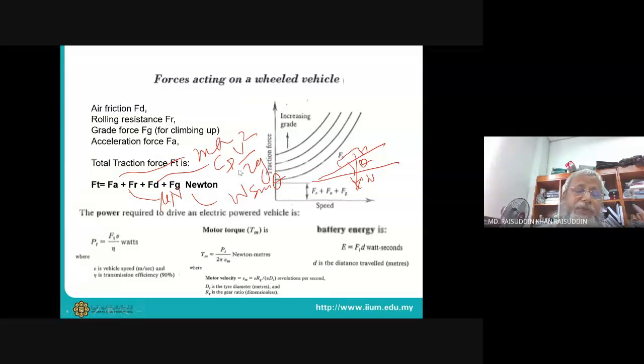And how much power do you need? So this is the calculation of the power. It comes from Ft, the velocity, and the efficiency of your motors. Motors, those we use, their efficiency is generally 80 to 85%. Then you can get the power of the motor. And we also need the torque calculation. You can see PT we have already calculated. So the mean velocity we know, then we can calculate